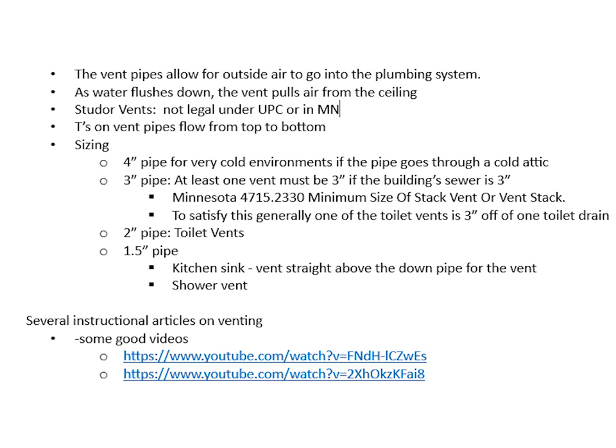Sizing: 4-inch pipe for very cold environments if the pipes go through a cold attic. 3-inch pipe: at least one vent must be 3 inches if the building sewer is 3 inches. This is out of Minnesota Code 4715-2330, minimum size of stack vent or vent stack. To satisfy this, generally one of the toilet vents is 3 inches off of one toilet drain.